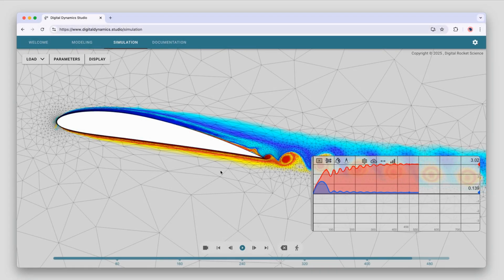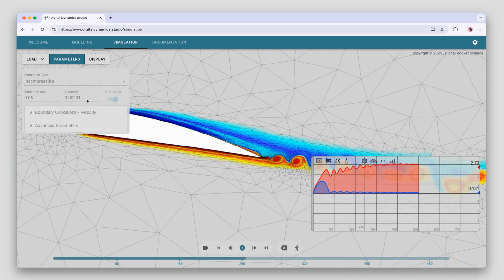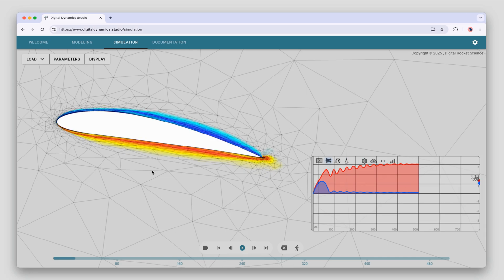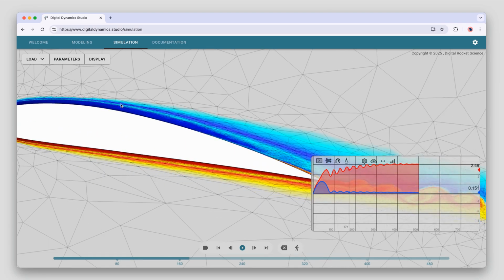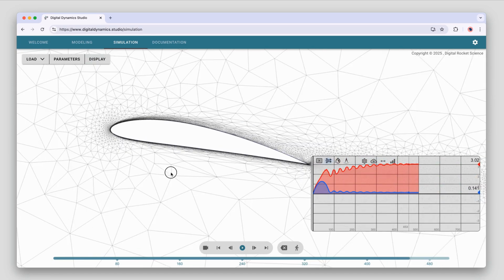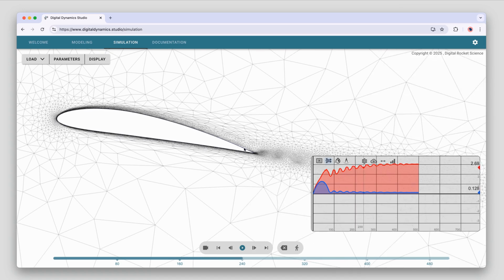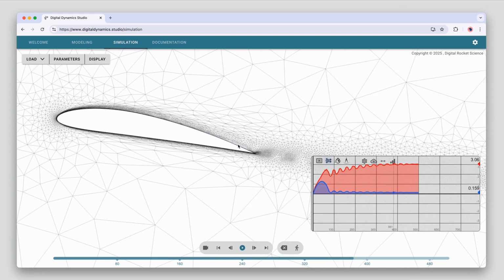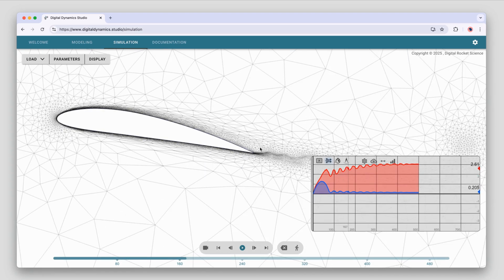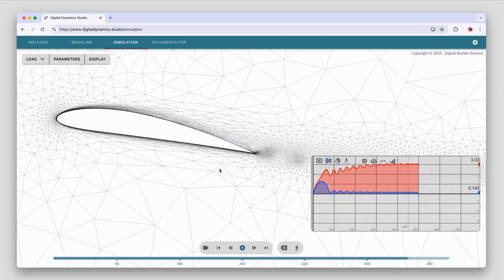So in this last simulation, if you remember, we had a very low viscosity, which results in a high Reynolds number. We turned the turbulence model on, lowered the time step size, and did the best we can to capture these kinds of high Reynolds number flows. Like I said, there are some issues with it. It tries to put a bunch of small elements near the boundary to capture the boundary layer features accurately, but it's very difficult. The mesh is large, so it probably didn't do the best job of capturing the true aerodynamics for an airfoil at this Reynolds number.